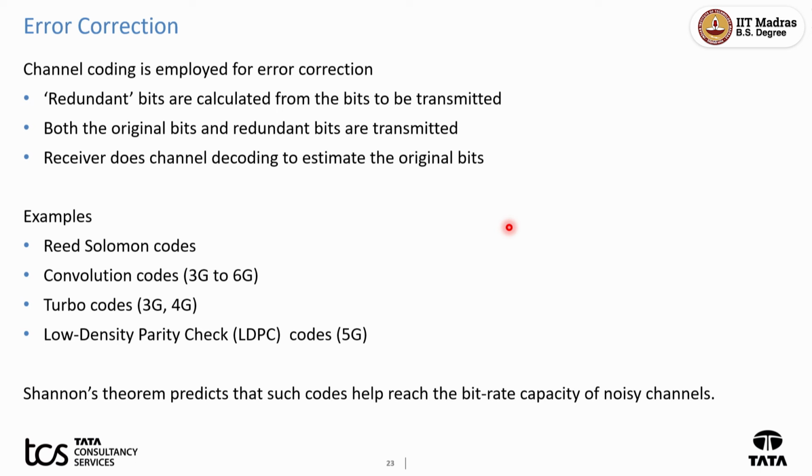But the idea is, one common way is simply called repetition coding. Send the same thing 10 times, 0, 0, 0, 0, 0, 10 times. Then all 10 signals have to go wrong for that to go wrong, correct? It's unlikely. If you average over them, the chance of going wrong will reduce a lot. But repetition is very inefficient.